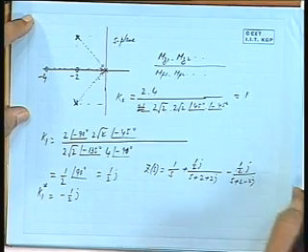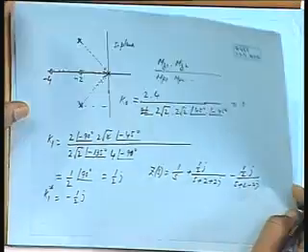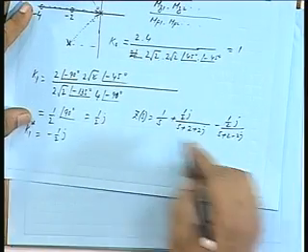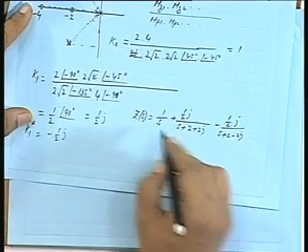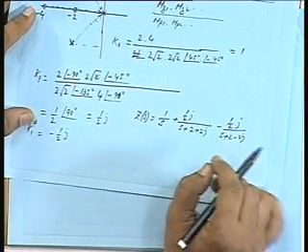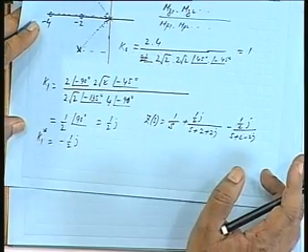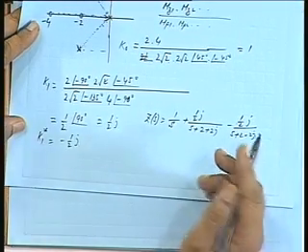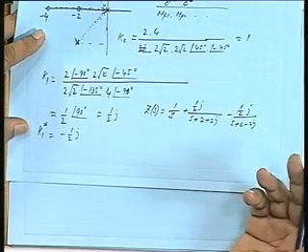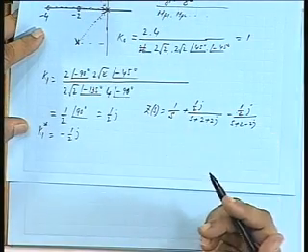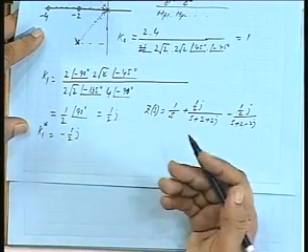Is that all right? If you are interested in knowing the impulse response, if I excite by an impulse of current, what will be the voltage like? It will be I into Zs, and for an impulse I will give you 1, so Zs itself will be Vs. So what will be the corresponding Vt? Just the Laplace inverse of this.